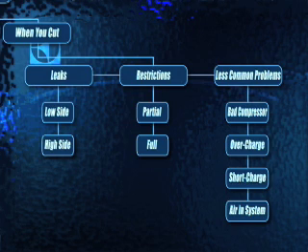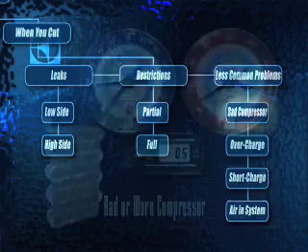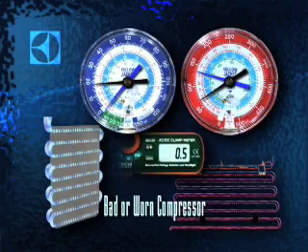These less common problems should not be overlooked, especially if the system has been serviced recently. A worn or damaged compressor could be the result of heavy contamination from a low-side leak. Has the system been serviced?